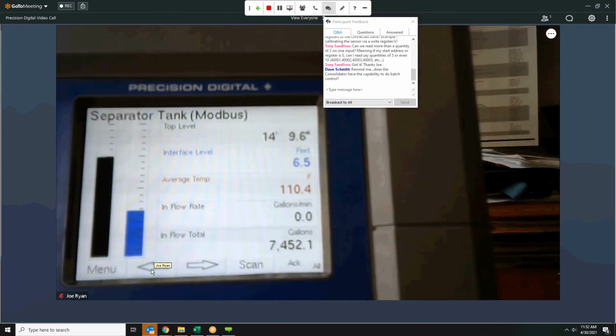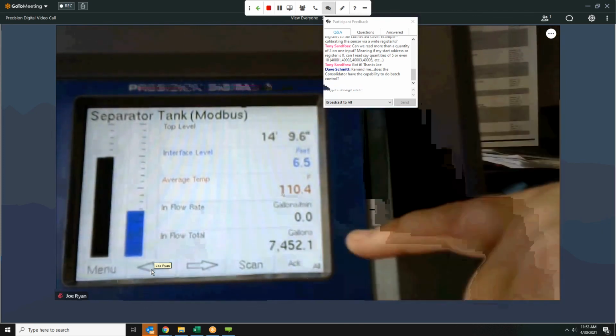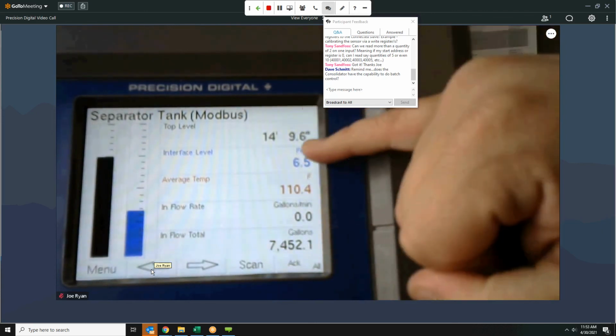If I now want to have relay outputs for alarms or 4 to 20 milliamps retransmitting back to my control room, I'm basing it totally on these numbers now. I'm out of the world of Modbus. None of that matters to me anymore. I just programmed that one screen to get my Modbus input set up, bring in that one variable, and now I'd set up a second screen.